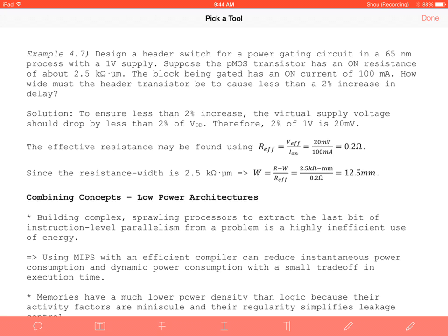But we're also communicating through Bluetooth or wireless to the sideline, so that your athletic trainer can see in real time whether or not somebody has a concussion. So one big thing is it has to consume less power, but delay is important. You want to get that information as quickly as possible. They have said that if it's greater than a 2% increase in delay, this causes a problem for us because of wireless protocols. So this is your constraint.